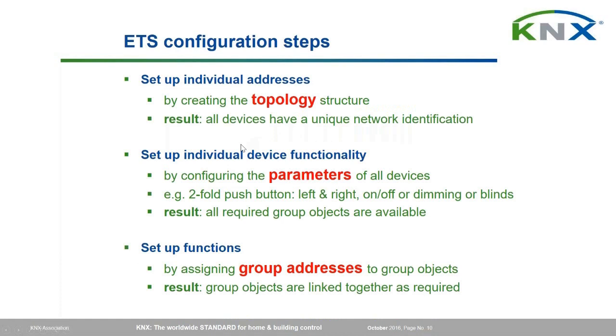Okay, then about ETS. Before I go into the second part, the demonstration, first a few things about ETS, so the actual configuration steps. So what is the first configuration step when you want to realize functions in a KNX installation? Well, you need to set up first the individual addresses of the devices, and by doing so, you create the topology structure of that KNX installation.